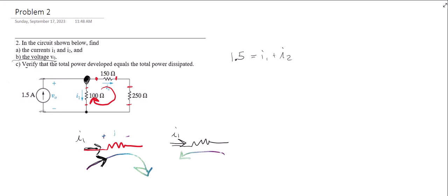So let's say this resistor is R1. If I were doing KVL in this first scenario right here, the voltage change across this resistor, remember Ohm's law, V equals IR, the voltage change across this resistor in scenario 1, so delta V, would be I1 R1. In the second scenario, delta V would be minus I1 R1 because my loop is going in the other direction.